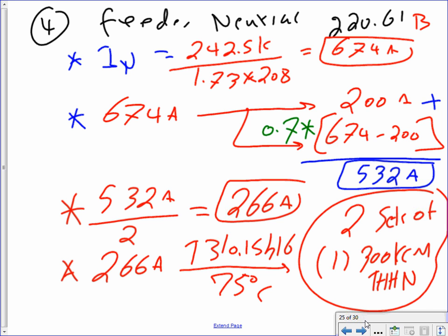Guys, let me give you a disclaimer. Karen, you never pull a 700 amp lighting panel. That's way too much light in one area. Did you guys hear me? That's a theoretical value. In real life, if you exceed a 225 amp panel, it's very, very recommended to split them into multiple panels. So in real life, the 700 amp, what do you do? Chop them by half and run two 350 amp panels. Or maybe chop them by 3 even and run 200 amp panels or 225 amp panels.